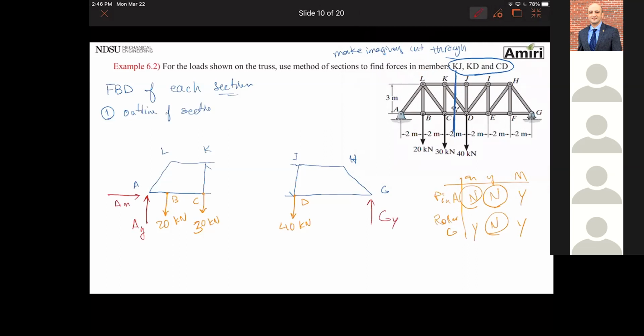Let me ask you this question. This is very, very common in bridges, and I covered this in my lecture too. Why do we have a pin on one side and a roller on the other side? If this is a footbridge, why do I have a roller on one side and a pin on the other side? Because the bridge will have to expand and contract. So it's for expansion, contraction, for deformation, for ground movement, all of that.